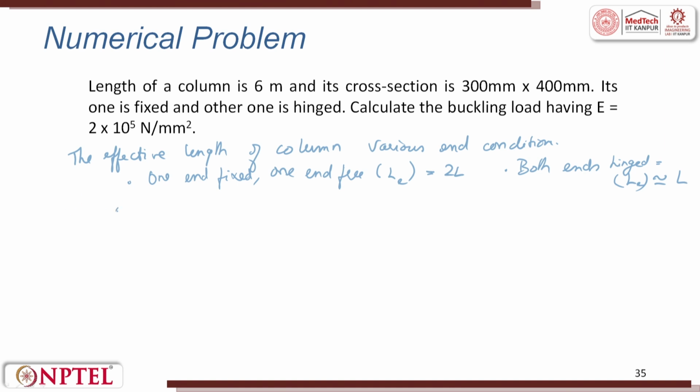If one end fixed and one end hinged, we will have LE, that is nothing but L by root 2. If both ends are fixed, the LE is going to be 0.5 times L.